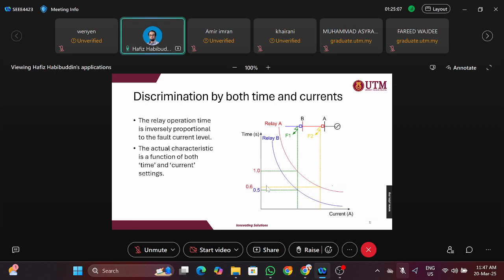But of course, if you want to adjust it, sure, no problem. We have 500 gain here, 1000, right? So this one is kind of fixed. You want 1000 to be faster, you can imagine that you want it to be 0.3 second here, fine. So that red curve needs to be moved down. You're going to have this somewhere in between. So in this case, 1000 is 0.3, 500 is 0.5.